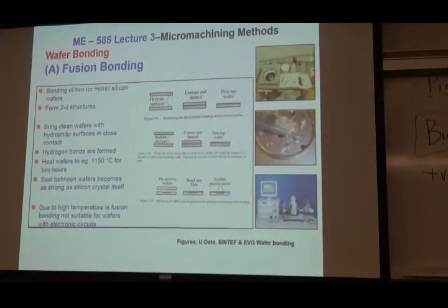Now that's where it becomes really weird, because at the back, nothing is polished. You can't even see what's on the inside. So there are tricks to put an alignment mark on this wafer and an alignment mark on that one. When you go to the clean room, you'll see our exposure system has an alignment mark, so the optics is in such a way that it sees both ways.